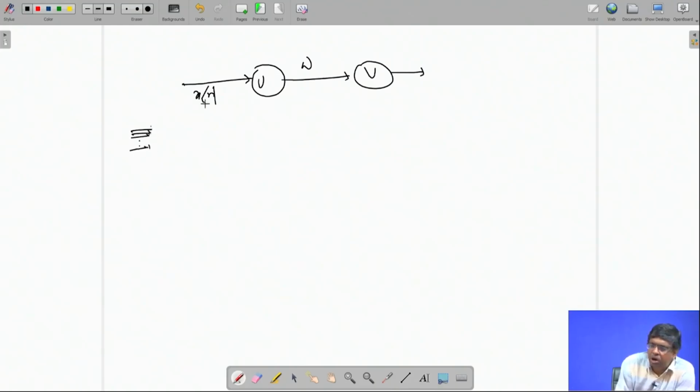So, it is a 16 bit word, all the 16 bits will come parallelly. One word means the whole data xn, next is another word, next is another word, they come through the bus. This kind of structure where the bits are parallel is called bit parallel or word serial structure.